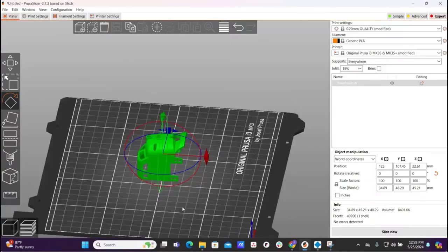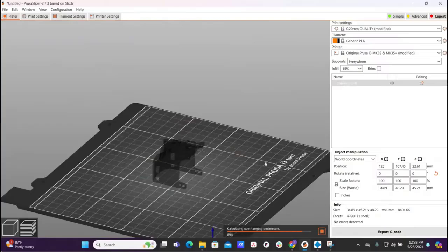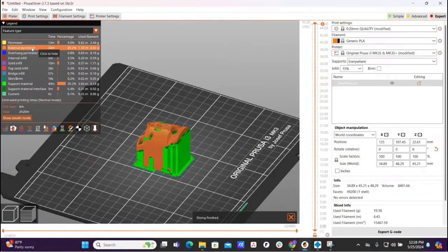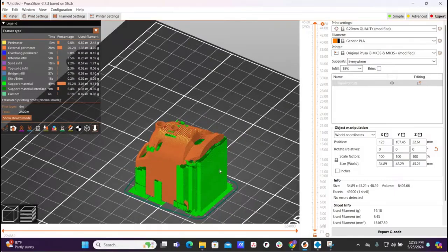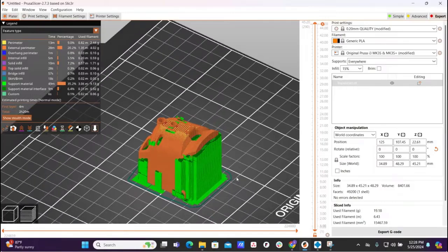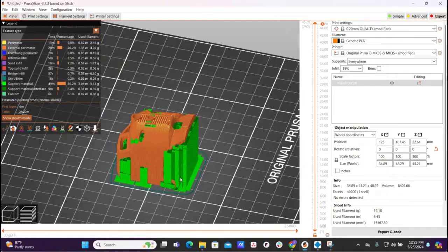It's not ideal. One thing that you have to keep in mind as well is when we slice this, the printers already have the support set up here. The printer would yell at us if I didn't have these support structures here. Now, these are just little temporary pieces of plastic, so you need to know what supports are, because you're going to have to use them at some point. You can't avoid it completely unless you're designing yourself and you make things modular, then maybe. But these are all going to get removed. So once you print your file, you're going to rip all these off, and what's left behind is going to be what you actually care about in your model.